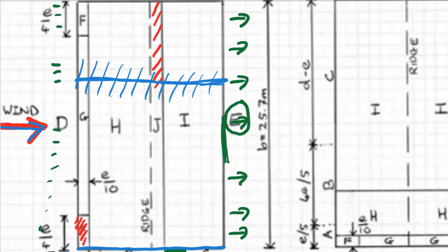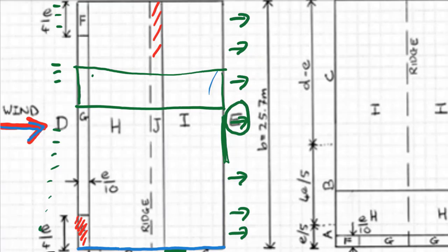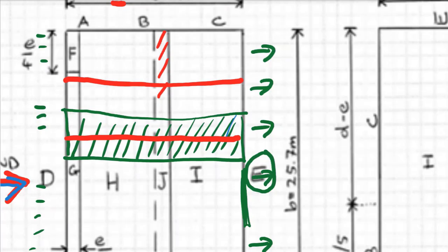So now we're going to analyze a portal frame running through, and we're going to then apply loads. So just to stay there again, we're going to apply a tributary width. So the bays are 5 meters apart. That means there's about 5 meters of load sitting on your structure, because the portal frame sits in the middle, but it receives 2.5 meters of load from one side and 2.5 meters of load from the other side, and then the next portal frame sitting there will receive something similar.